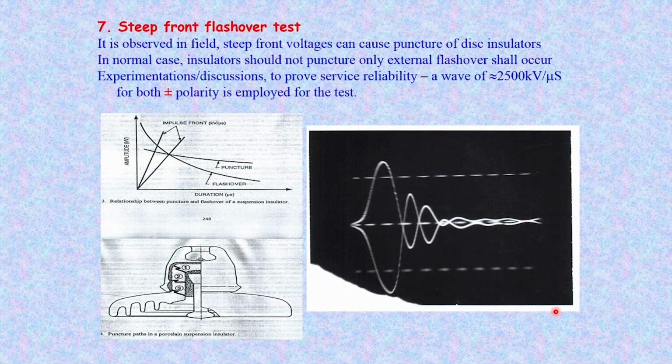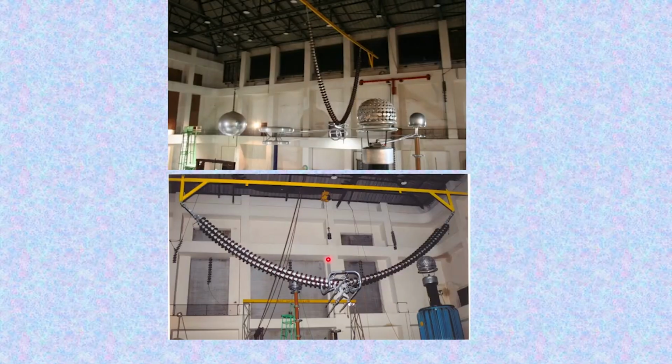So, voltage distribution is very important, to check whether the potential is properly distributed across each insulator in the entire string. In case it is not properly done, at the line end here, the first 3 insulators are being shielded by a corona control ring, and further, if proper shielding or proper grading is not done, the insulators near the line end, 1, 2, 3 or 4 insulators, could see more stress compared to the ground end or the insulators at the middle, which in the longer run in the field could shatter, and the voltage distribution could be disturbed. So, that is the reason to make the entire string uniform.